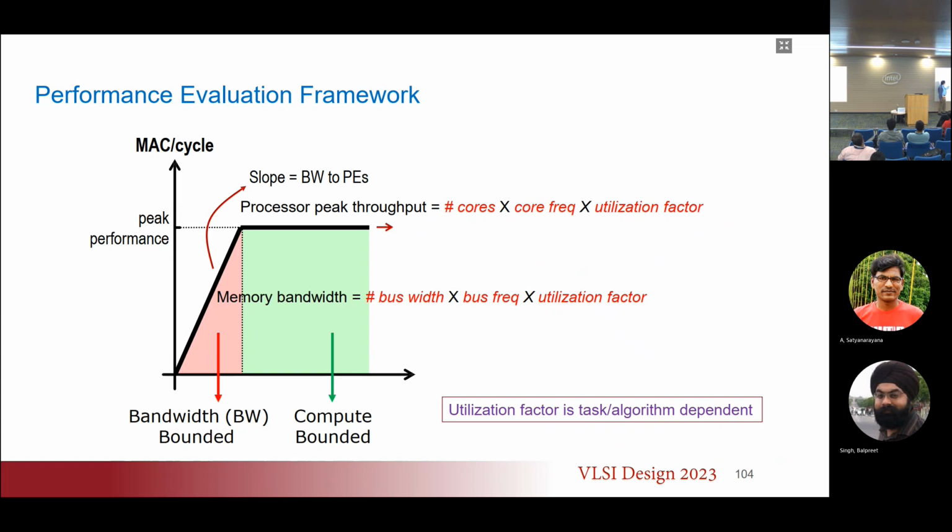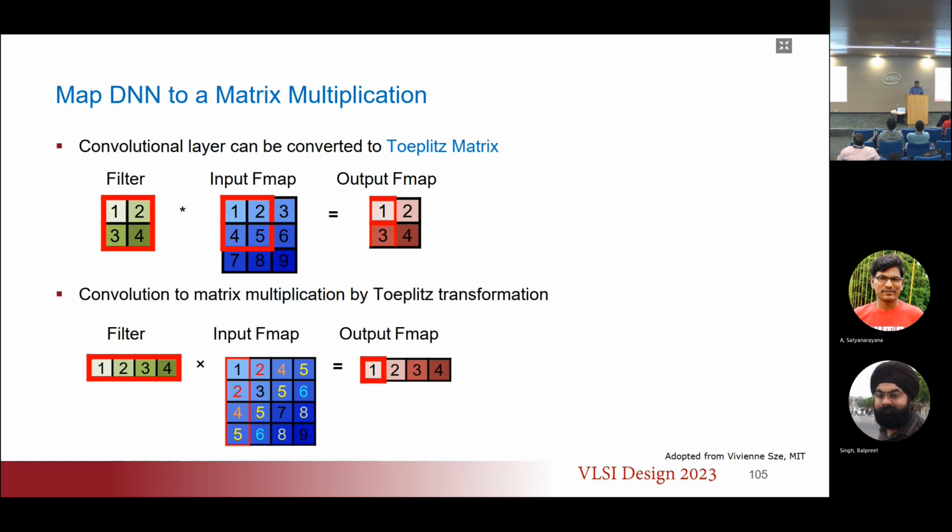And here it's saying that I have caught up with my memory bandwidth, but now I'm processing element limited. So where is the sweet spot of operation? Right here in this corner. We don't want to operate here. We don't want to operate there. We just want to always operate here. And that would be the ideal decision point in making accelerator design decisions.